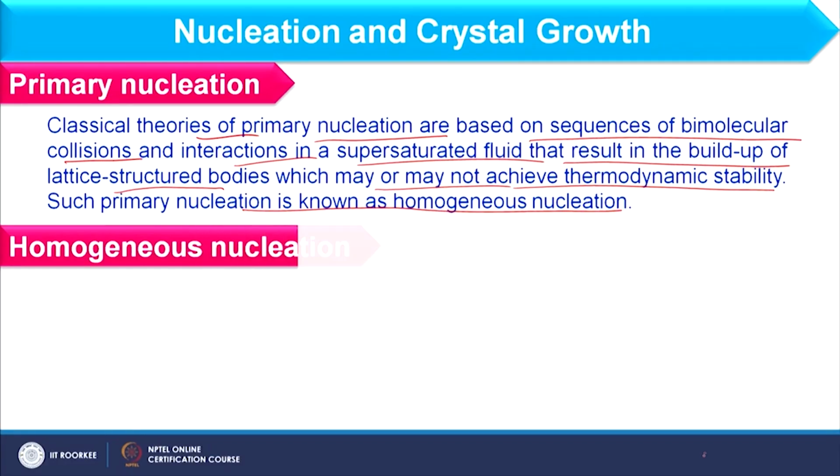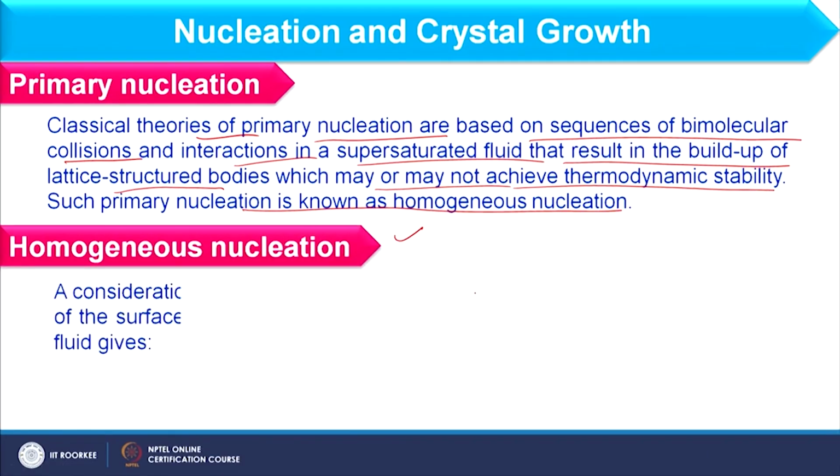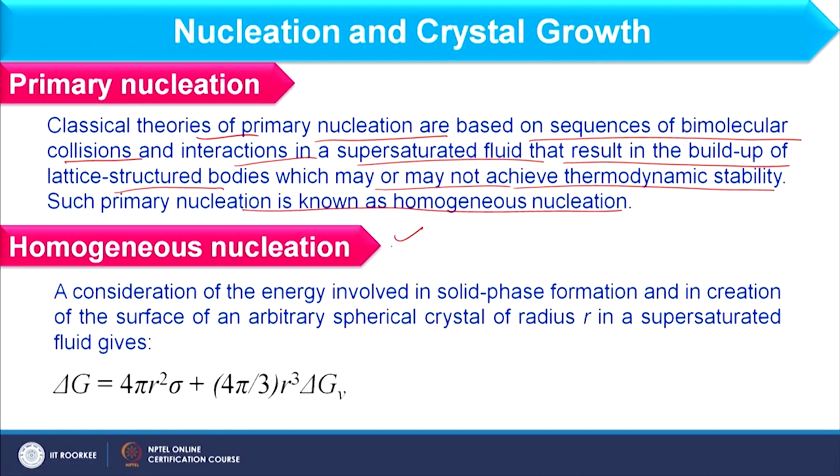In homogeneous nucleation, we consider the energy involved in solid phase formation and in creation of the surface of an arbitrary crystal of radius r in supersaturated solution.